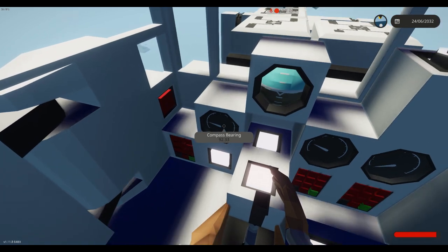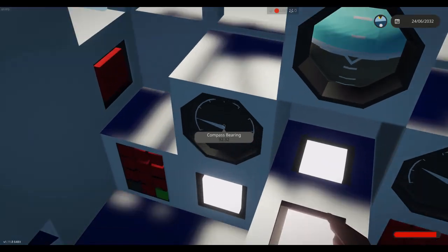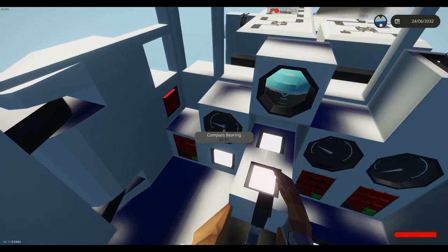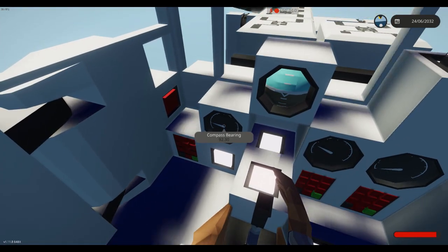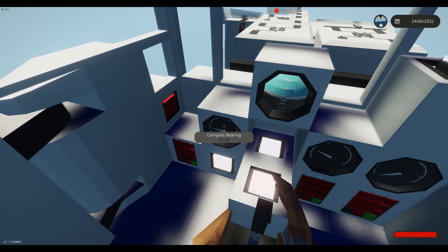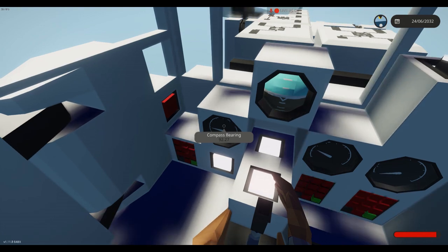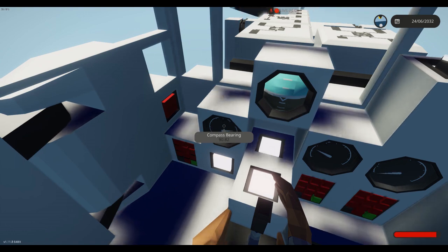Currently, I do not actually like this. I think the proportional value needs to be slightly larger. This is just working too slow, so I might double the proportional value. I think it's at 0.003, we might make that 0.006, or maybe even more, we'll have to take a look at it. For now, I'm going to use my rudder inputs to try and get it closer to 90 and see what happens.